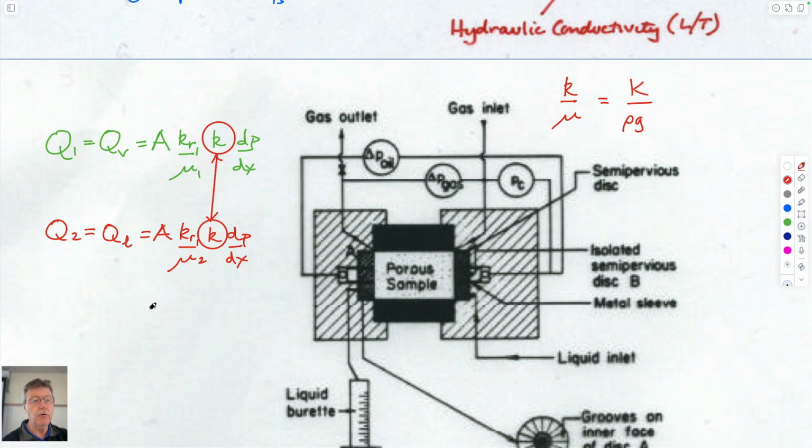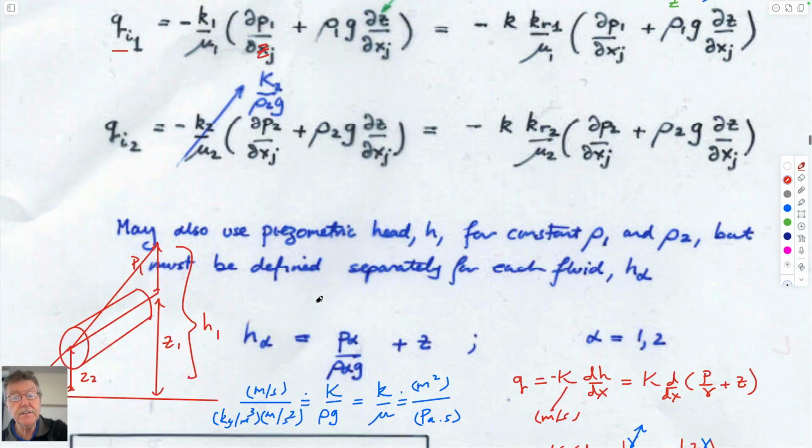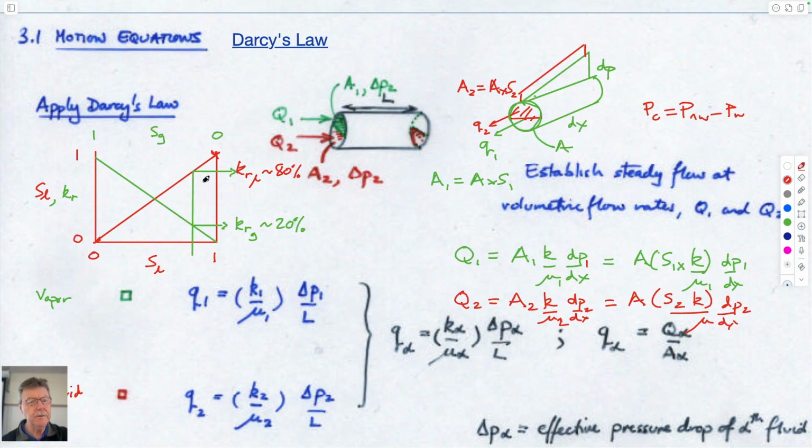So this is our formalism for this. Relative permeability would be different for each component, as we suggested here. It's very similar to this, but we'll talk about the fact that this is a very simplistic view of relative permeability. So we plotted saturation versus saturation and then called it relative permeability, which we can do, but we'll look for a slightly more sophisticated way of defining this.